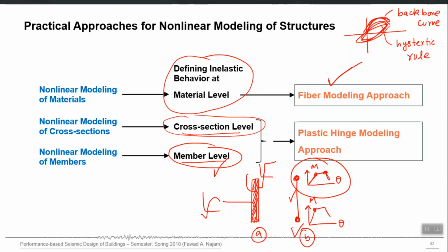So you will see that if you want to calculate this point mathematically, you will require Fc prime, you will require Fy, which are material properties, you will require E, you will require cross sectional properties like cross sectional dimensions B, D, and a lot of other inputs are required. So the whole member behavior is just combined in the form of one curve.